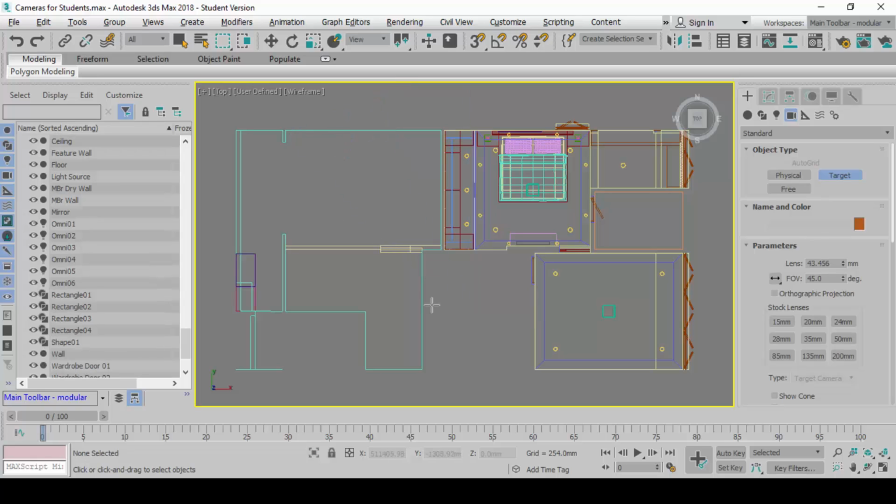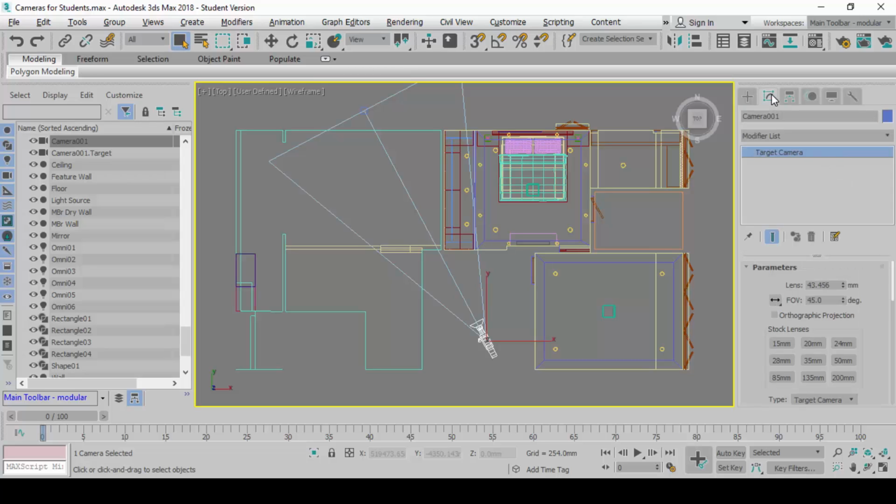Okay, I'll repeat one more time. You definitely need me to. Click, drag, and let go. And then you have created the camera already. Just that. Very straightforward. Now, the moment you have finished creating it, can you go to the Modify tab now and look under the parameters header. So we close off everything and then we expand only the parameters here.